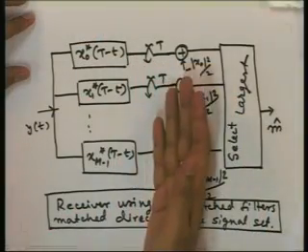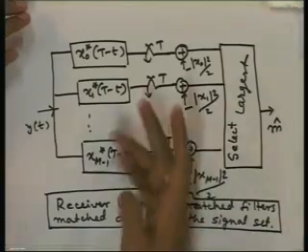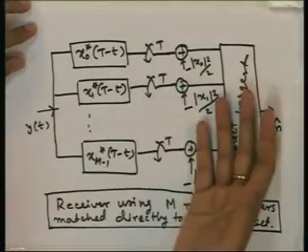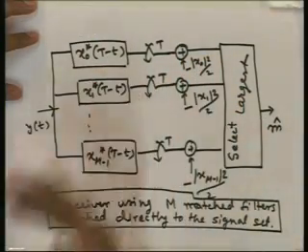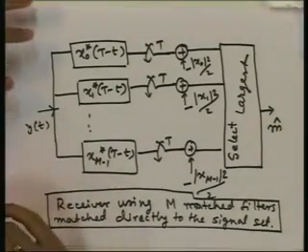Now, how do we verify that it will be really nearest to that? Suppose this is largest. Can you say that this will be the nearest? Yes, we can, because we have proved that this actually does the optimum, and this is equivalent to finding the nearest point in terms of the distance. So, if you just choose the largest here, this will give us the minimum distance point. This will tell us which signal is the nearest to the received signal.